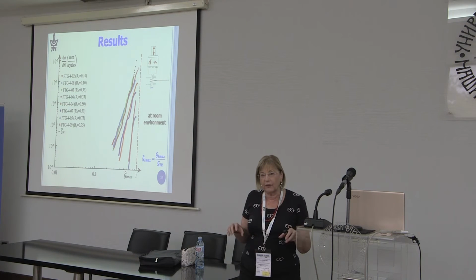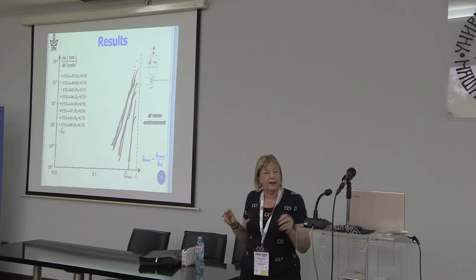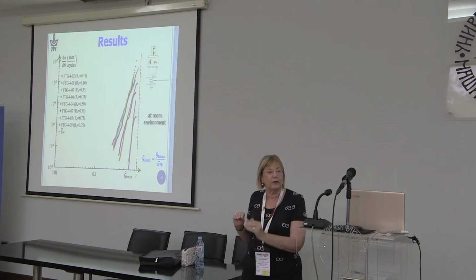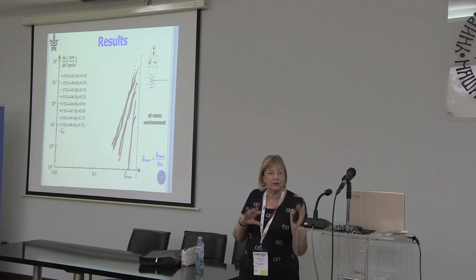DCB is for mode 1, and there are 2 mode 2 specimens, ENF, end notched flexure, and CLS, calibrated end loaded split. And then there are 2 mixed mode specimens being used, MMELS, mixed mode end loaded split, that ISO is working on.